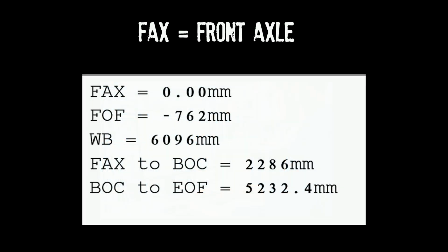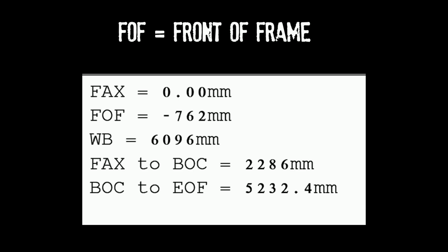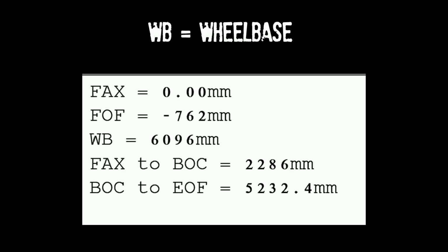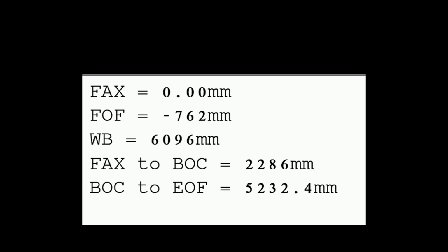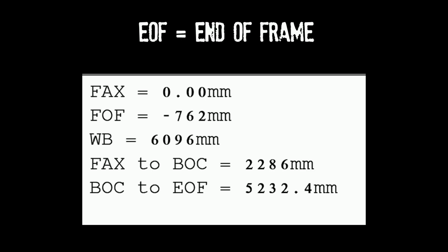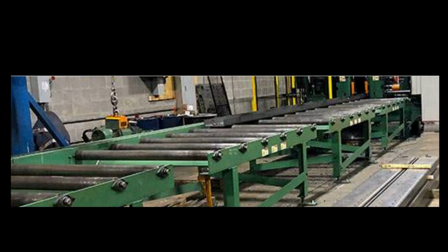Truck manufacturing engineers prepare frame drill data by accounting for all component locations. A reference point, known as the 00 station, is used to define drilling locations, often originating at the center line of the front axle or the frame's front, depending upon the OEM. Dimensions can be communicated using either metric or customary units of measure.